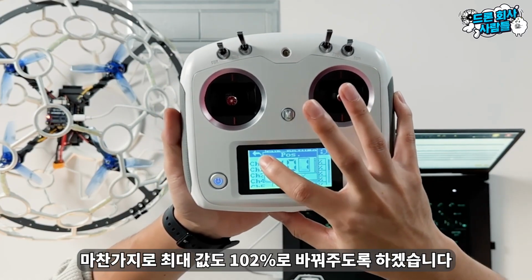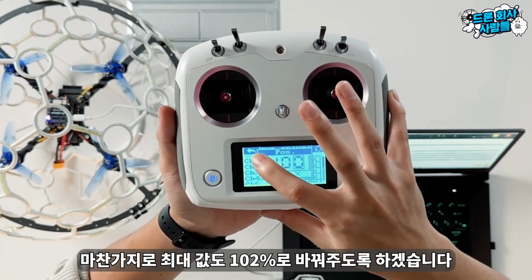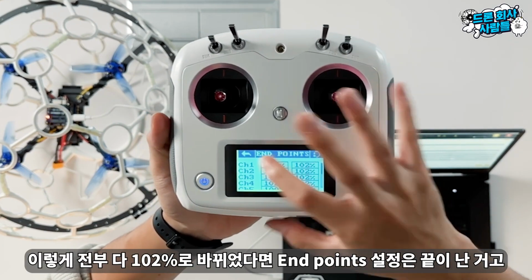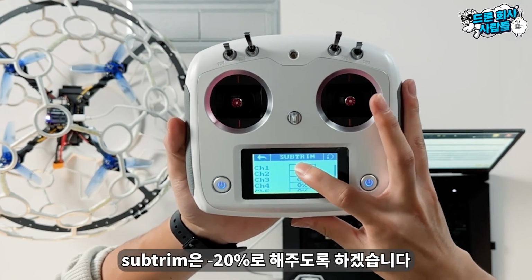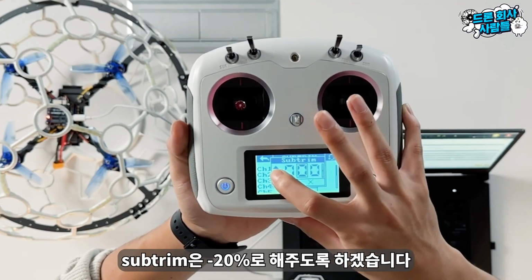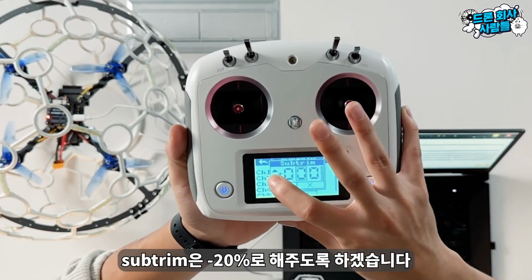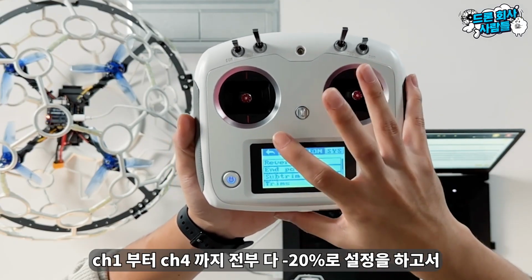Similarly, we will change the maximum value to 100%. Once everything has been changed to 100% like this, the endpoint setting is complete. Next, the sub trim. We will now set the sub trim to -10%. Set all channels from 1 to 4 to -10%, then exit to the initial screen.